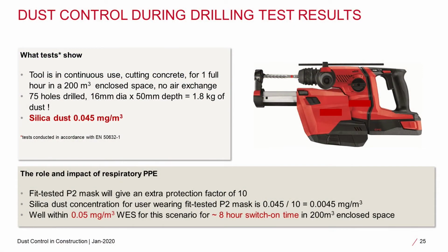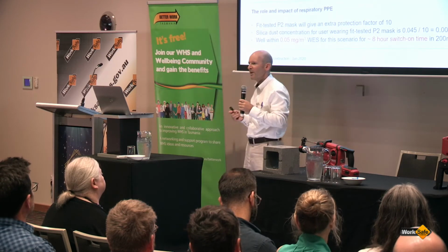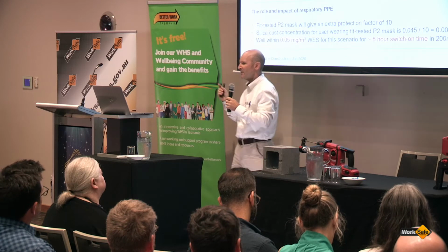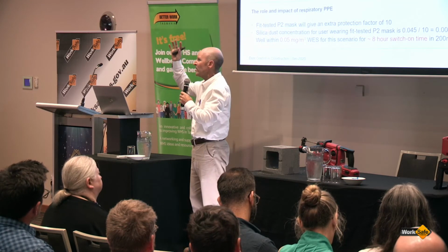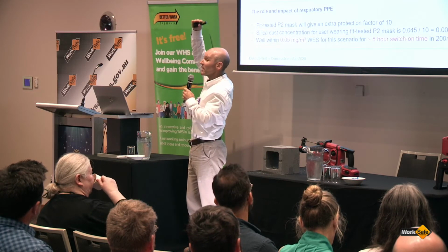And then our favorite that we just looked at, that Neil helped me with: as soon as you fit these small drills with onboard extraction units, you really control the dust situation extremely well. Because for plumbers and electricians working overhead on top of scissor lifts, the hidden danger here is that your breathing zone is really, really close to this application.